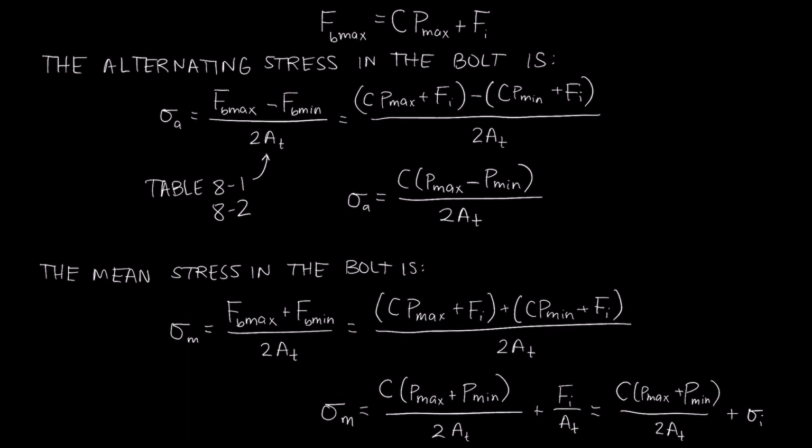In the Peterson Stress Concentration Factors book, there's an observation that typical bolt failures will happen about 15% of the time under the head of the bolt, 20% of the time at the first fully formed thread, and 65% of the time at the first fully engaged thread in the nut. And so for the most part, we would expect to see failure, if it's going to occur in a fastener, in the threaded portion of the fastener. And so that's why we use the tensile stress area here.